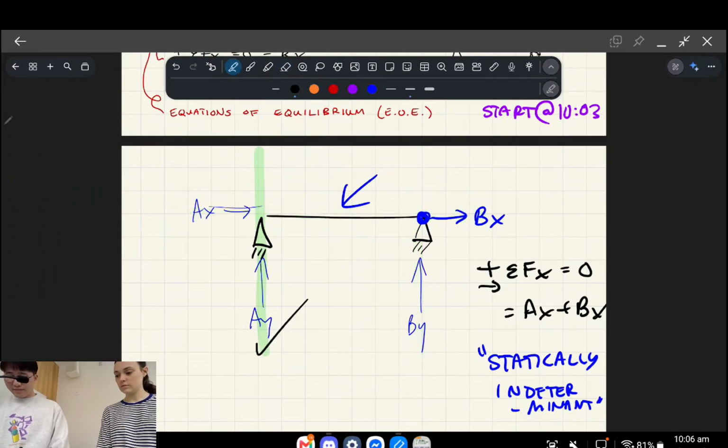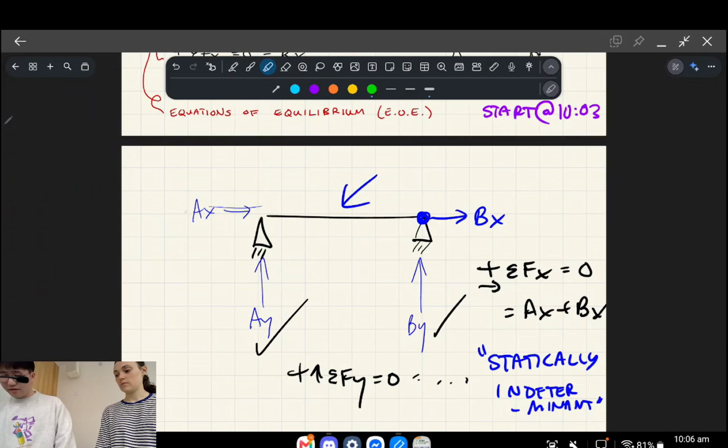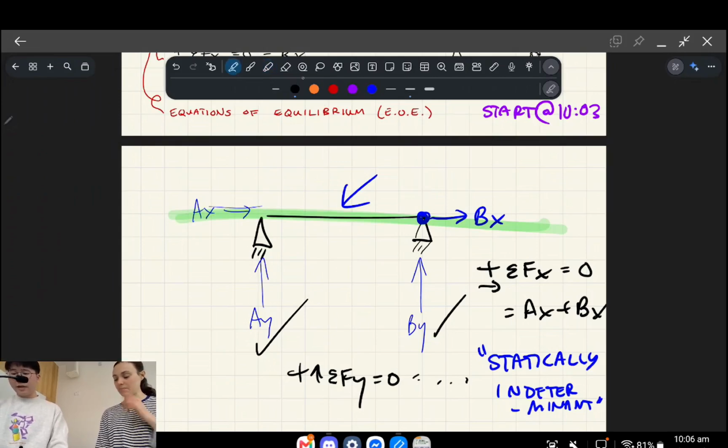Let's say you do that, and then you do the sum of the forces in the vertical direction is equal to whatever, and then you can figure out BY. So it's exactly the same, except now you've got these two horizontal reactions that you can't distinguish between, because since they coincide as lines, there's no point you can pick which will distinguish them with the moment equilibrium. So you can only figure out the x coordinate.